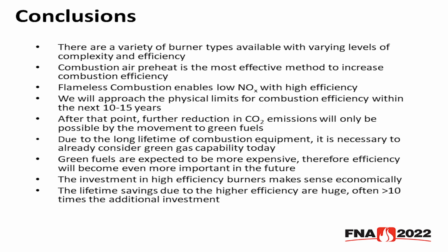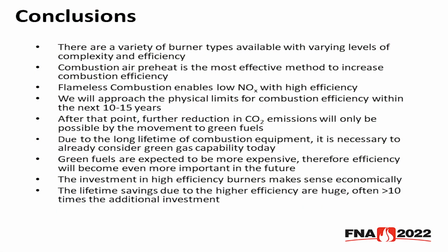So to sum it up, there are a variety of burner and tube technologies available, varying levels of complexity, efficiency, and cost. Combustion air preheat is still the most effective way to improve combustion efficiency. Flameless combustion enables low NOx with high efficiency, so we can have the best of both worlds.